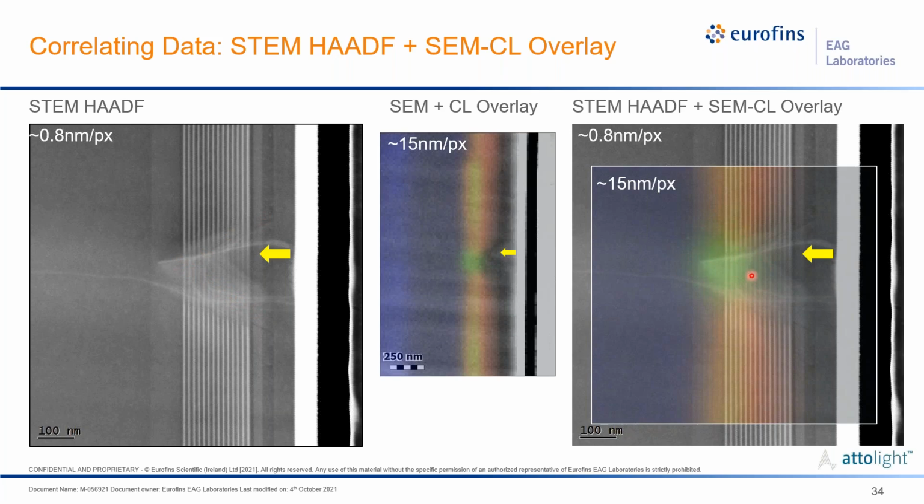So maybe it's related to the non-polar multi-quantum wells here, grown on the non-polar facets of the V defect, or something of that nature. It is very surprising, however, that we have these threading dislocations, and it doesn't really seem to be decreasing the intensity of the CL emission very much.